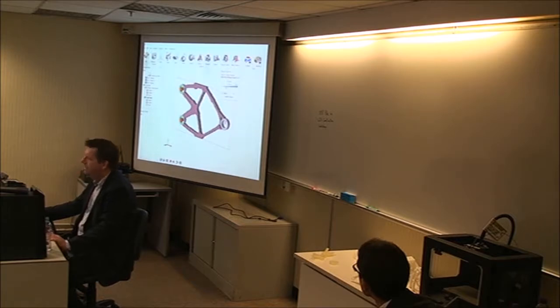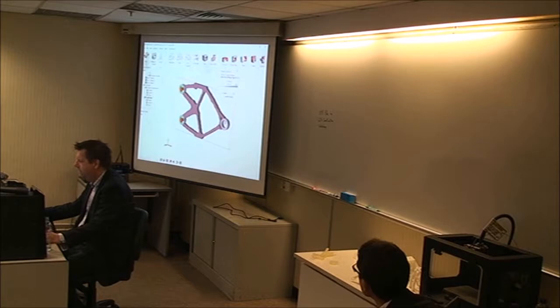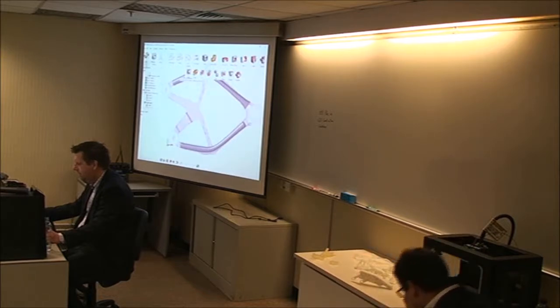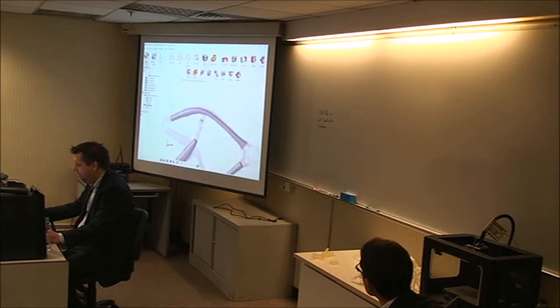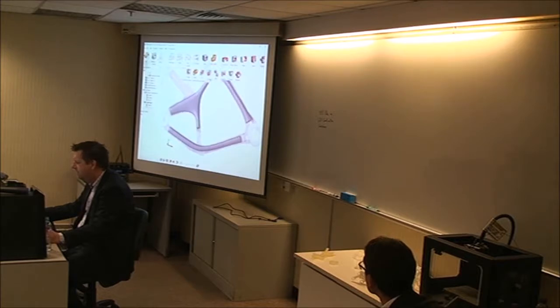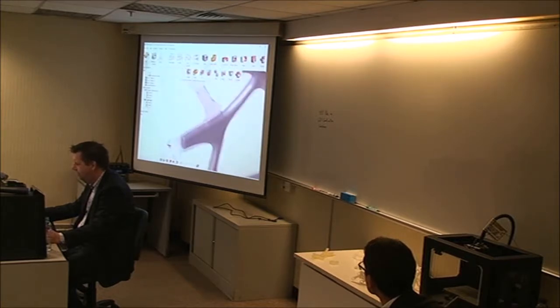Conscious of time, so I'm going to use that and go into the PolyNURBS to try and demonstrate that for you. So go into geometry, PolyNURBS. To prove it wasn't a trick before, I can just start sketching over my structure. I've done a few of these now, so I'm getting quite fast. And this wrap tool does 90% of what I normally want to do. And just doing this with conventional CAD is virtually impossible.